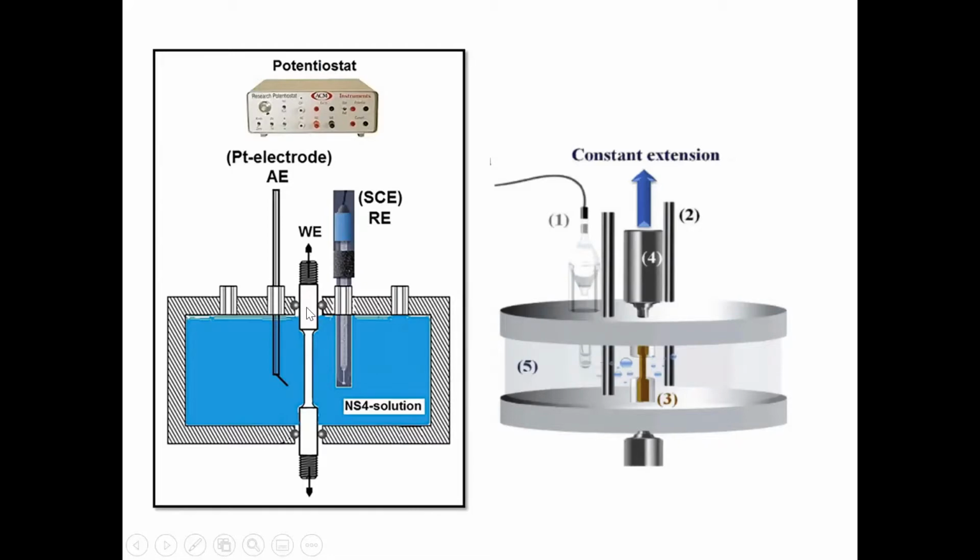We can apply, for example, cathodic protection, like we saw last week. And now we can see the effect of cathodic protection on the ability of the material to withstand stress corrosion cracking, because we apply the CP, the cathodic protection, to the specimen. At the same time, we're stretching it in the testing rig. And we're going to do the slow strain rate method, so we can ensure this will fail within about 1 to 2 days, maybe even just a few hours, depending on how fast we pull the specimen.